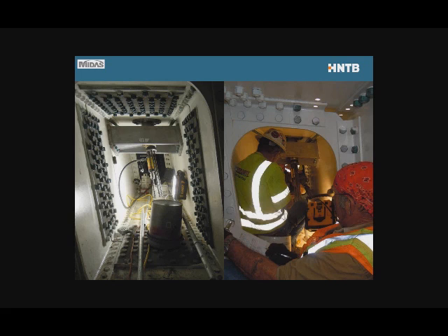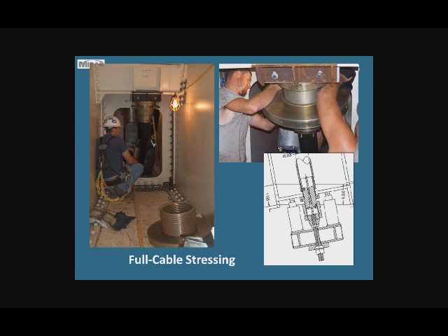This is inside the Lake Champlain Bridge, which was only, I think, 4.5 foot deep. You can see the very light stressing equipment that is sufficient for this strand by strand installation. Now it is possible to stress the whole bundle.